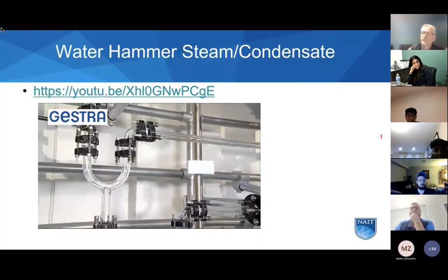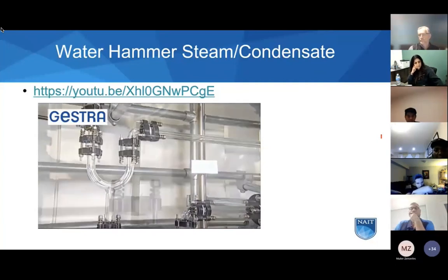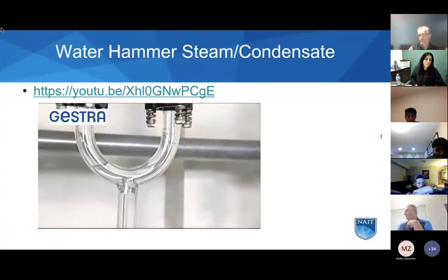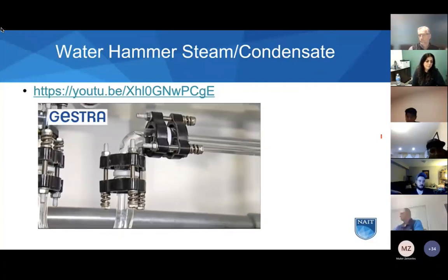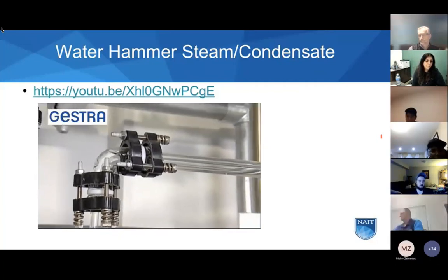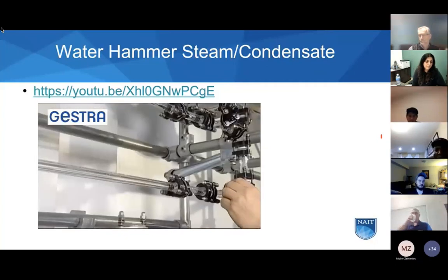Having the siphon downstream ensures that there is always a steam bubble in the horizontal part, and the water flows along the bottom. Through their volume, the steam bubbles at the top of the tube form a buffer space, which minimizes the water hammer at startup and allows the startup process to be initiated faster and with less risk.